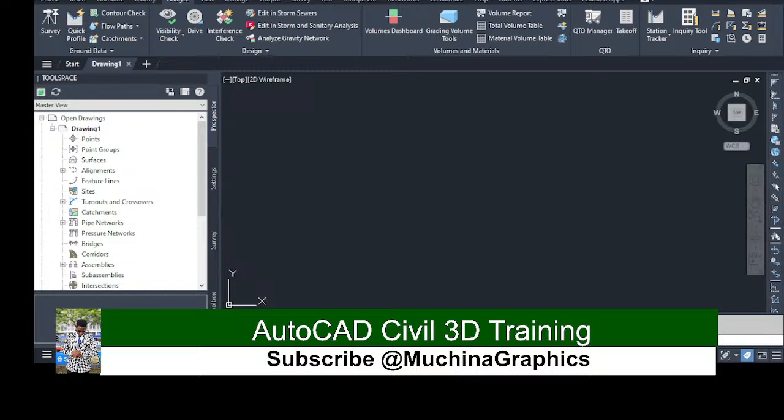So we're now in Civil 3D. You'll notice that it is much like AutoCAD. However, Civil 3D includes specialized tools, that is tool palettes and ribbon. Most of our tools are under the Home tab, including creating ground data, alignment, profile, and corridors. You also see the tool space. This is where Civil 3D stores and organizes your design objects like surface, alignment, and pipe network. So the first thing that we're going to do is import our data.